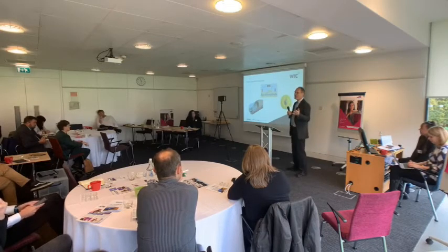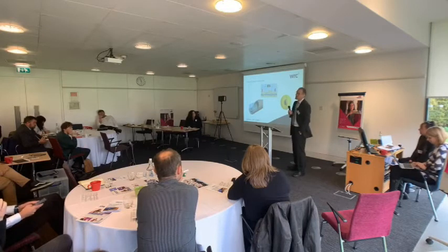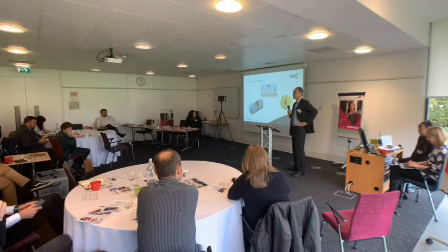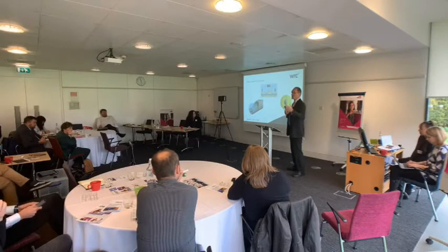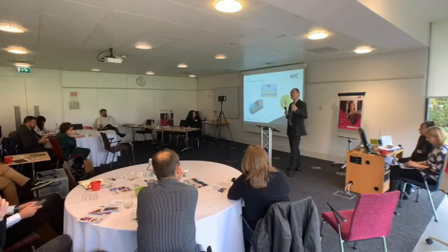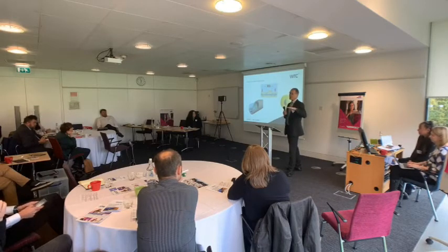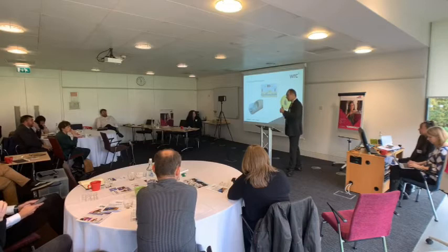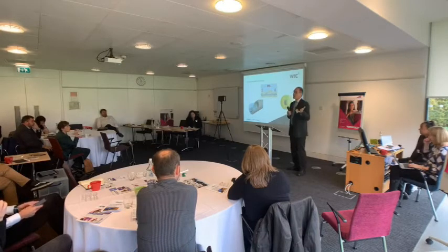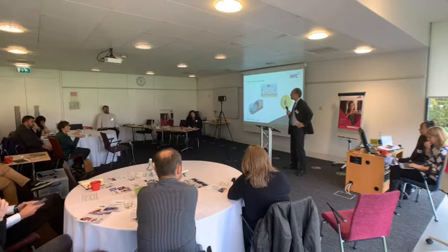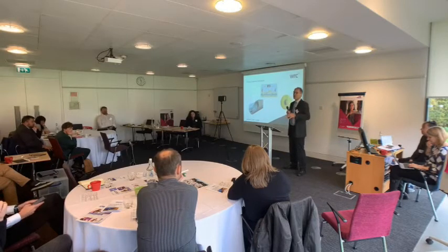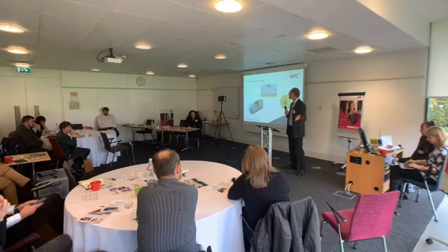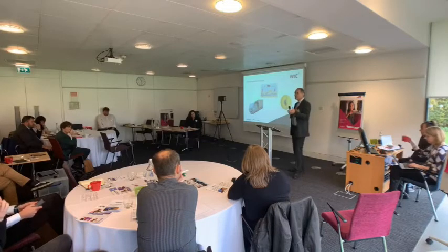I think it's fair to say that for many years trunk mains have not been seen as a problem for leakage, and I guess that's partly down to the fact that they are large, strong structures. Typically, if they're going to fail, they'll fail catastrophically, but thankfully that's quite rare. So people in essence believe that we don't see leakage from them. People do walk lines. Traditionally, that was the way of finding leaks in trunk mains, walking along the ground, spotting the damp patches or the green grass in the summer, and identifying where leakage is.